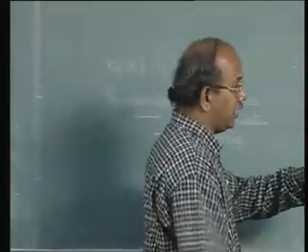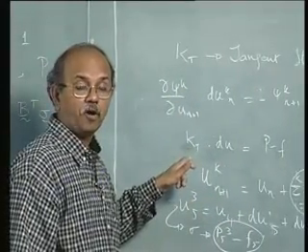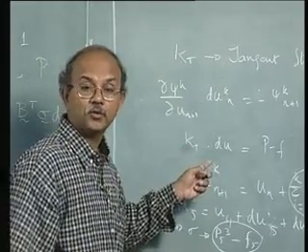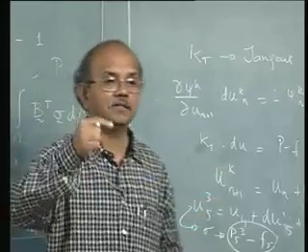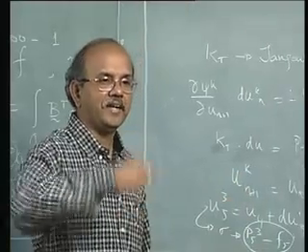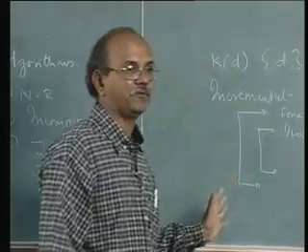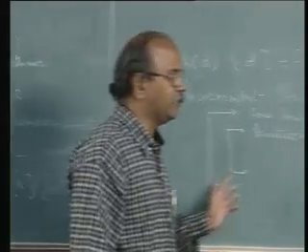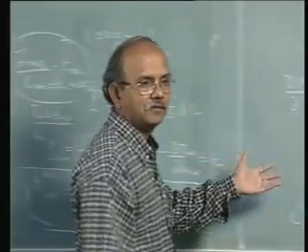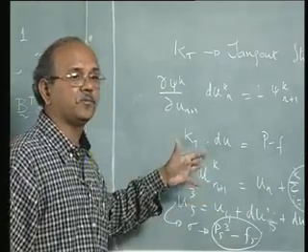Now, every time I do this in a Newton-Raphson scheme, I form tangent stiffness. Forming tangent stiffness takes time. Then I solve this equation. So in every iteration, I solve an equation, or in other words, every iteration is just equal to that of a linear problem. So if a linear problem takes a second, you can understand how long this would take. Is that clear? That is why nonlinear problems take tremendous time.